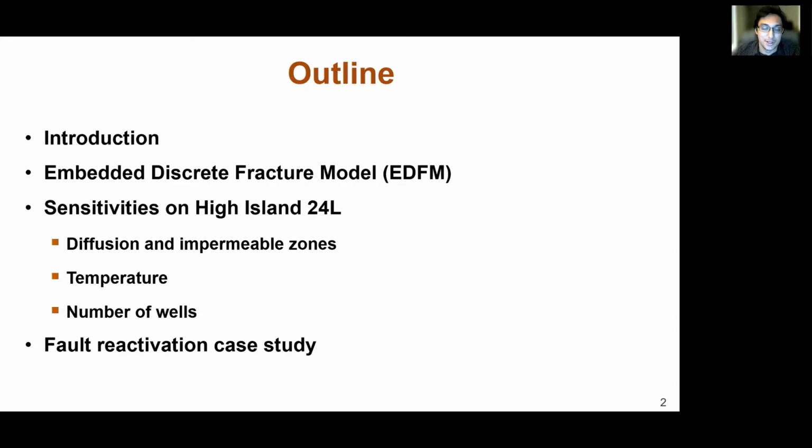CO2 storage. Then I would like to discuss a little bit about the embedded discrete fracture model that we use, EDFM. Then I'm going to be presenting some sensitivities we did on the High Island Unit 24L, where we basically tested the effects of diffusion, here molecular diffusion, and how we handle the impermeable zones within the storage aquifer.